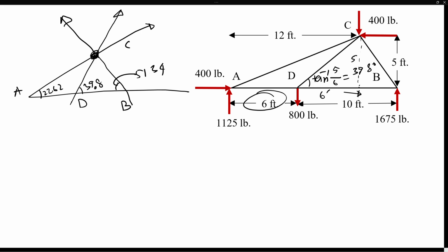So here we're looking at point C. We're not looking at A, D, or B. So at point C, we have 400 pounds here, and we get a vertical force here, 2,000 pounds. And we get all these different components. So this one is simply CA, and so on for DB. Now if we do summation of Fy and Fx, then we can calculate this DC.